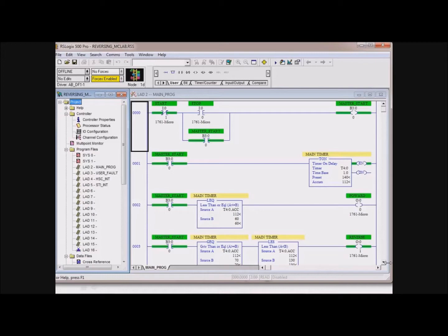Well, when you start a motor, they give you what they call full load current. It's rated in amps. That's how much current the motor will pull if it's running at its rated horsepower. The start current on a motor is 6 to 8 times the full load current.